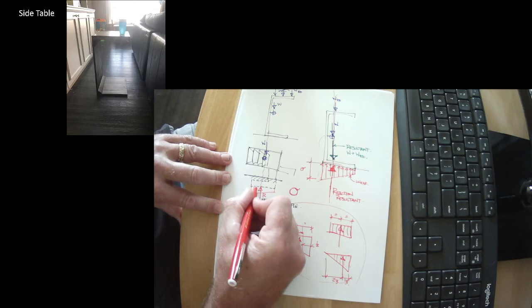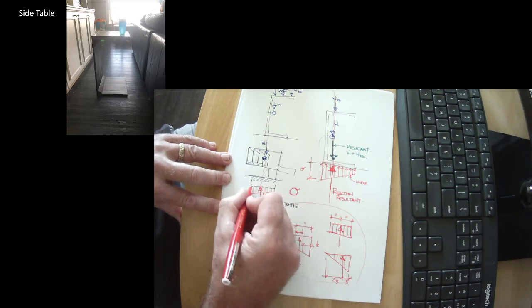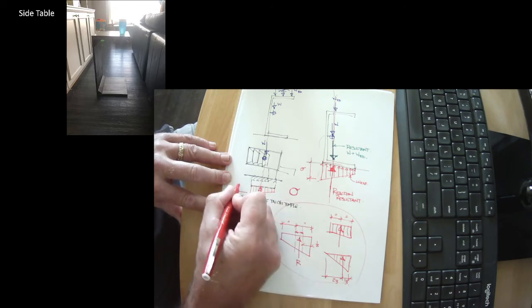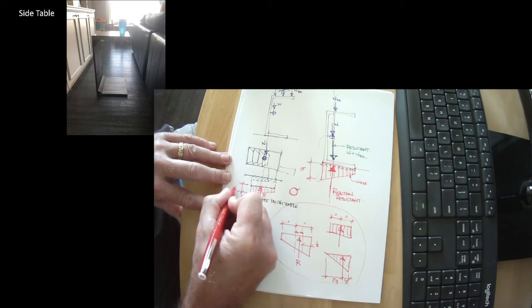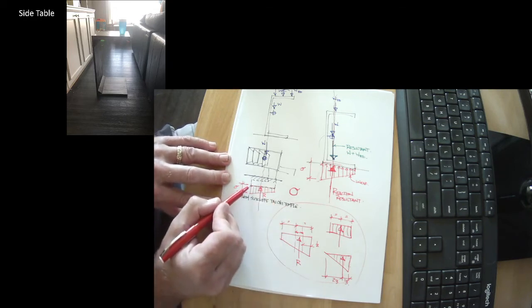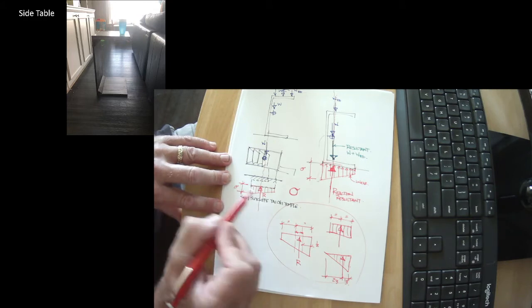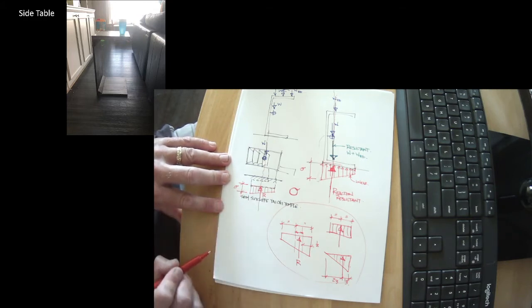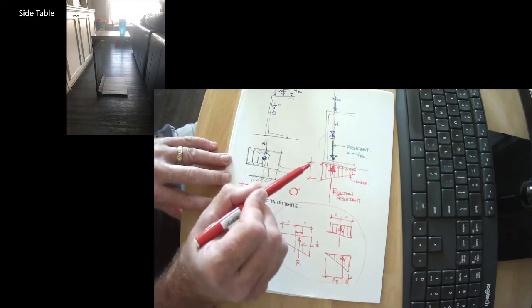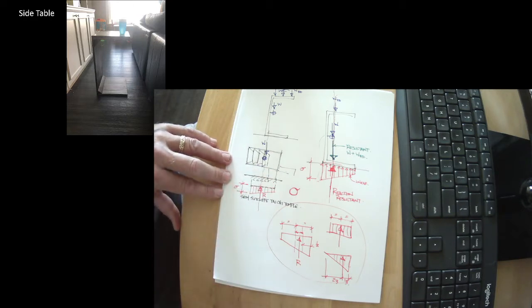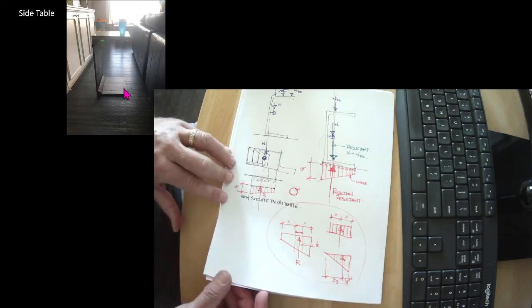And we have a trapezoidal bearing stress under our big giant footing. And we had to make sure that the bearing stress at the tip of the footing did not exceed the bearing capacity of the soil. So, a very real world example of exactly that problem.